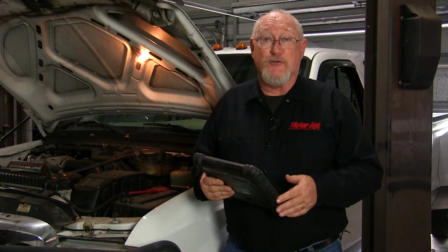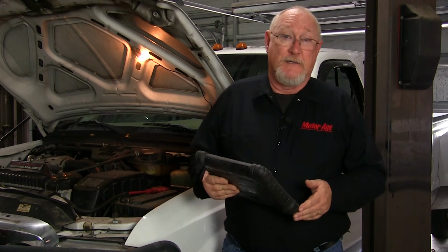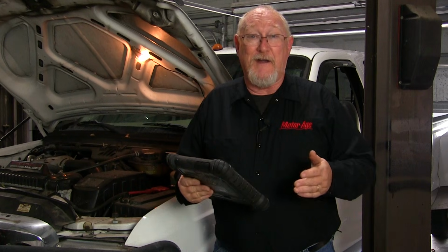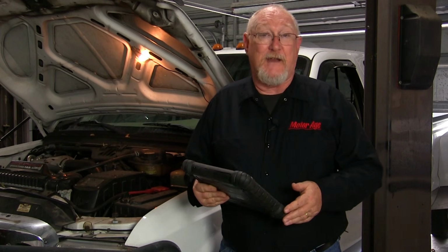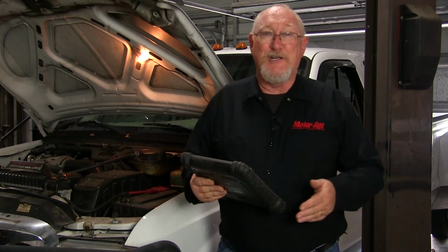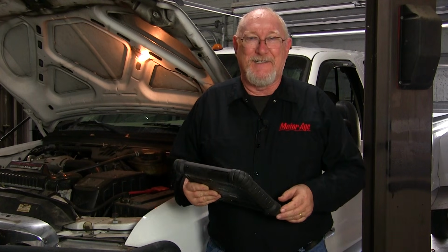The ABS module showed no response. And since that's the only unaccounted for module on the CAN network, I think we're all pretty sure that that's the missing module. Now I want to point out here that since all 3 of this vehicle's networks pin out directly at the diagnostic link connector, there is no gateway module in the system.